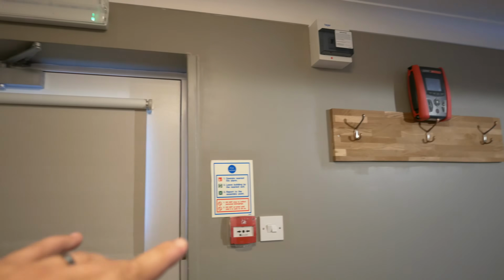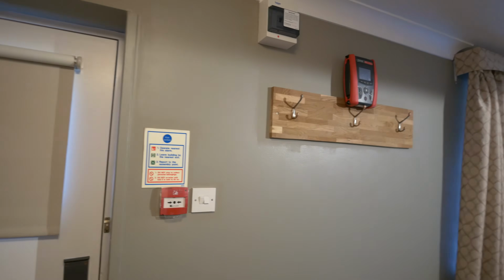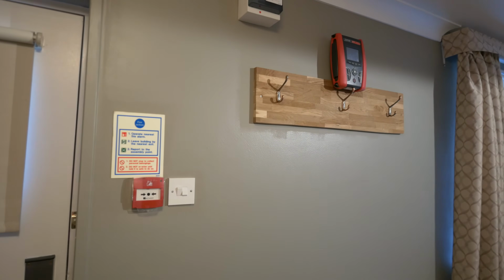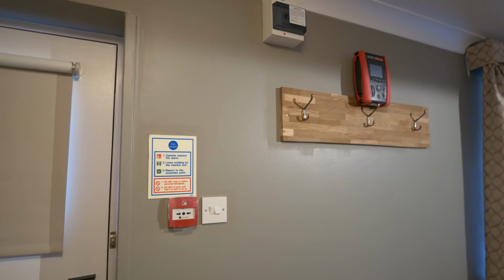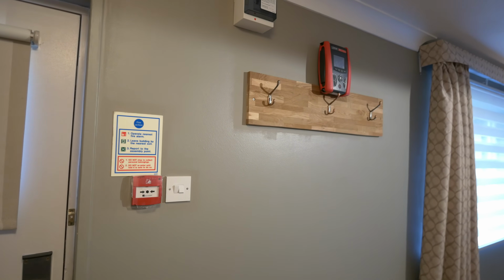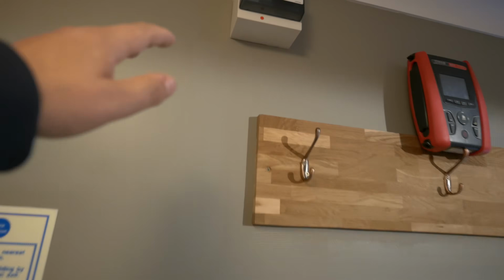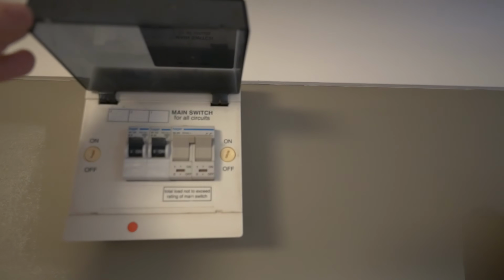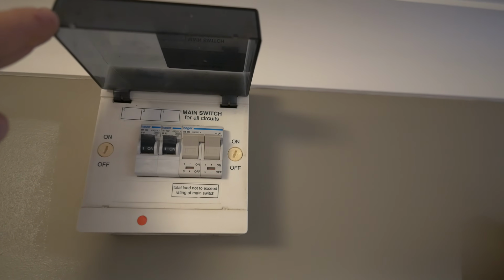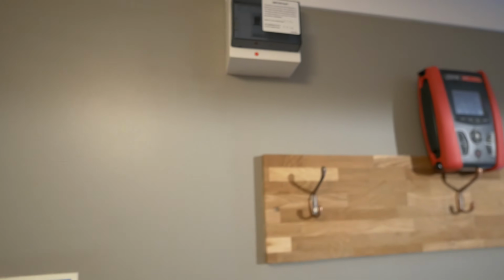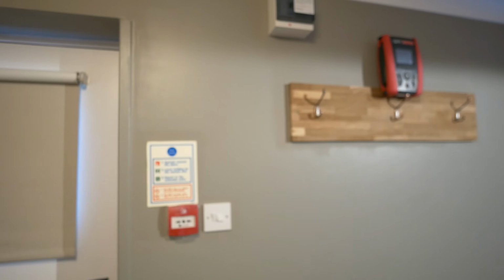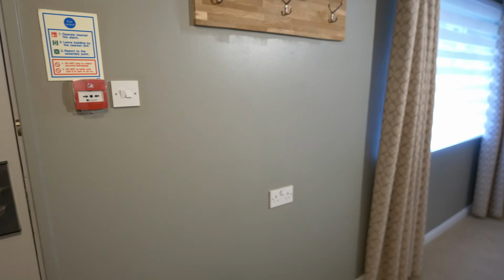Let's have a look around the accommodation and see exactly what we're faced with. That's the first thing I recommend anyone does when they're performing an EICR. You need to have a good look around and see exactly what you are faced with. First and foremost is the consumer unit. You can see up here we have a main switch, and then a couple of circuits unlabelled. We've got a B32 and a B6, so I strongly suspect that they are going to be the power and lighting, probably a ring final circuit and